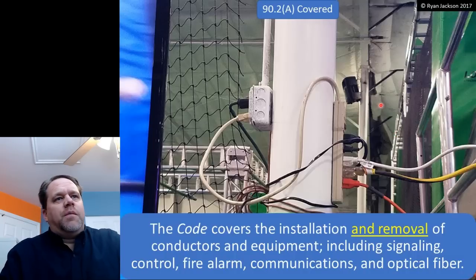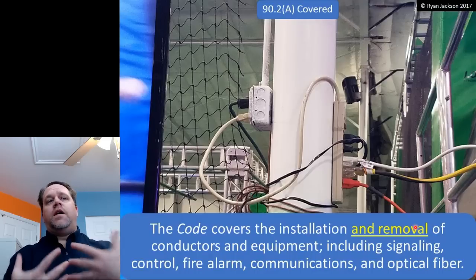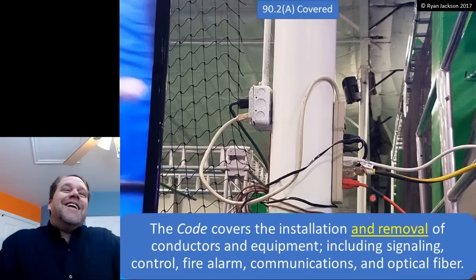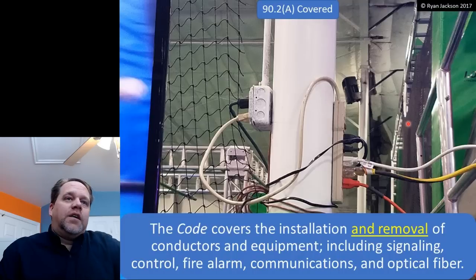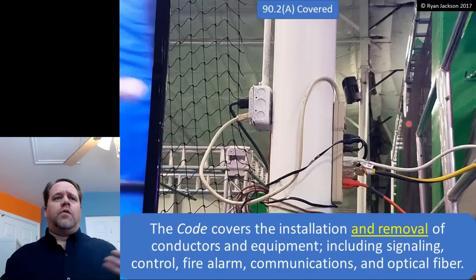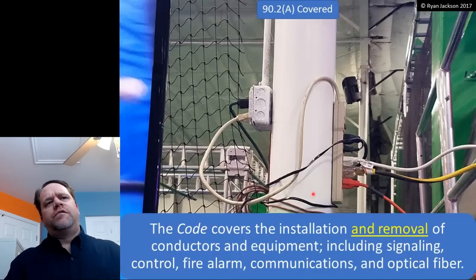What a great code violation, because when you look at these relocatable power strips, they all have instructions, and they all say the same thing. They say, number one, don't plug them into each other. And number two, don't mount them to anything. Don't hang them on a wall. Don't hang them on a post, which of course is why they all have mounting holes in the back. But I looked at this and I thought, man, what a great code violation, because 110.3(B) says, hey, look, if you have listed equipment, you have to follow the listing instructions, and the listing instructions include the product instructions. So this is a violation. But then I stopped and thought about it, and I looked at what these cords were being used for. And none of it was installed electrical equipment.